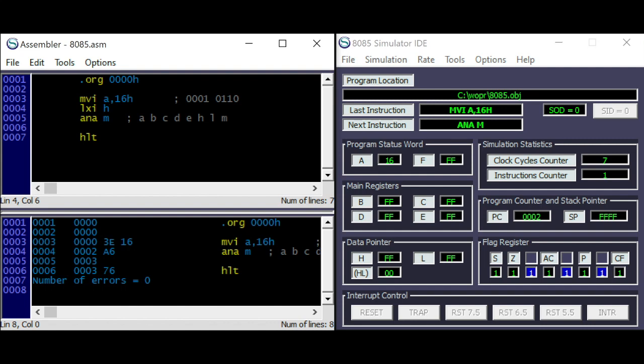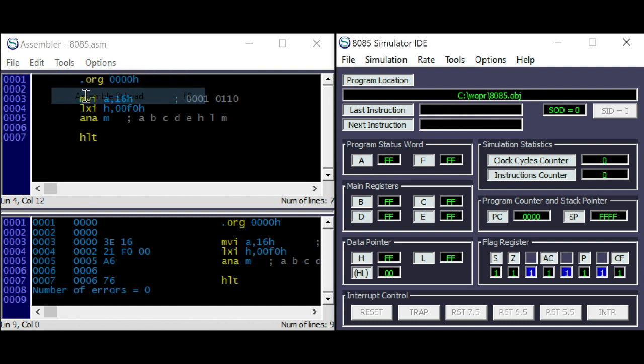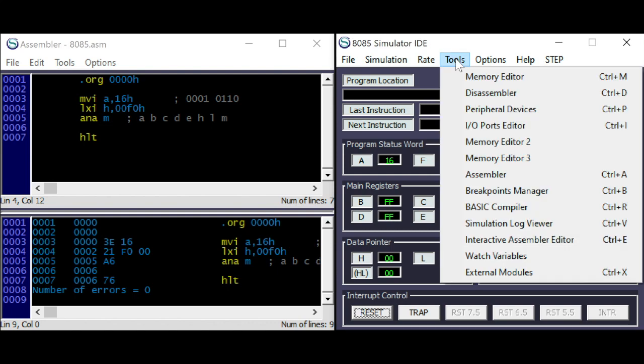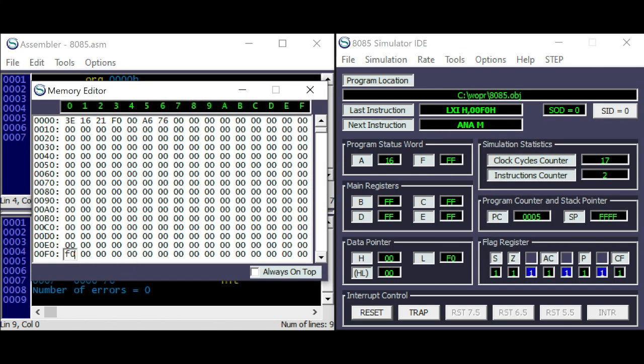Let's load double register H. Let's take number F0. So, and in F0 I will specify here F0. So we will cut the lower 4 bits. There's only 1 left. Zero flag is 0 and parity flag is 0 because there's only 1. Okay, do it again. So this time we want only the lower bits. And we're keeping 6 here. Zero flag is 0. Parity flag is 1 because 6 is 4 and 2. That are 2 bits.